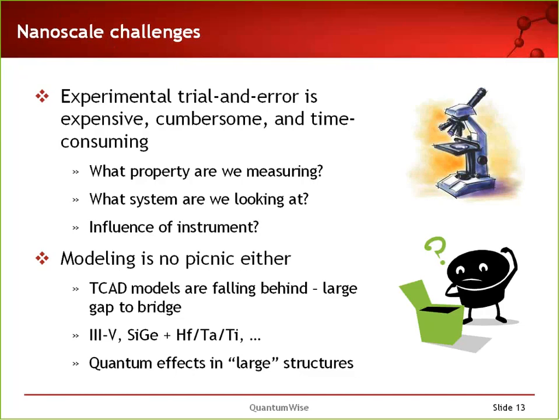But even worse, when you're looking at the quantum effects, the probes that you are coming in with onto this very, very small device are actually of the same size as the device itself. So it's not even certain that you're measuring an intrinsic property of the system. If you imagine an AFM tip coming in and pushing around atoms, are you measuring just the atoms, or are you measuring the AFM tip plus the atoms? So the influence of the instrument is very strong, and you also can't just look at the system with a microscope and know exactly where your probe is located. It's very difficult to know what property you're actually measuring and what system you're really looking at.